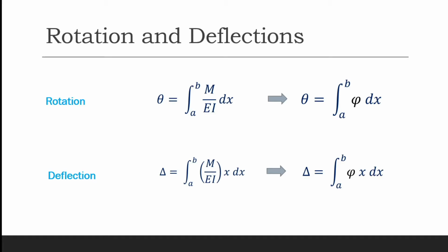In fact, this quantity is quite useful because it helps us compute the hinge rotations for nonlinear analysis, where we have to provide a moment rotation curve rather than a moment curvature curve. So we assume a certain hinge length, multiply the curvature by that hinge length, and we get the moment rotation values for that hinge.